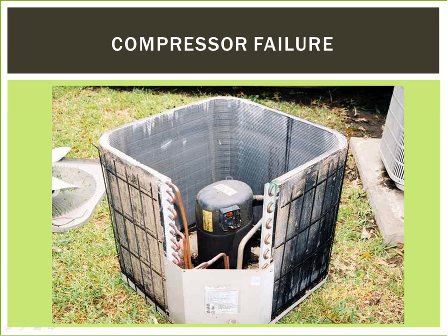The compressor moves the refrigerant through the system. It takes refrigerant from a low pressure and compresses it into a high pressure. If the compressor fails, flow and compression stop. If the compressor fails electrically, it will not run. There will be no vibration and no noticeable temperature difference in the body of the compressor or the system lines and components. If the compressor fails mechanically, you may still feel vibration from the compressor running, but system temperatures will be the same throughout and system pressures will be equalized.